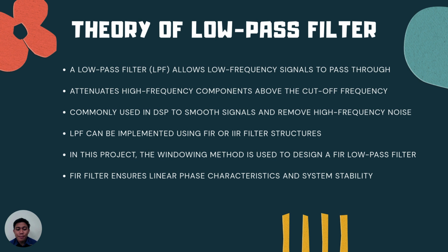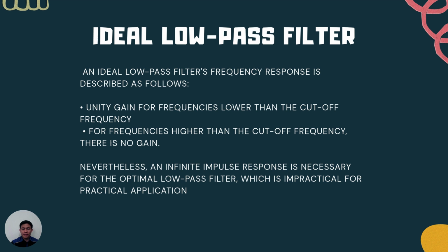Low-pass filters can be implemented using FIR or IIR filter structures. In this project, the windowing method is used to design a FIR low-pass filter. FIR filter ensures linear phase characteristics and system stability.